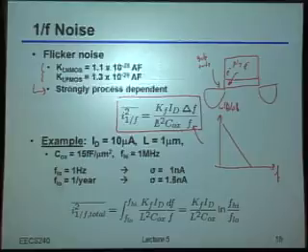Yes? Are those KFs just for strong inversion? Okay, so this is kind of bias point dependent. Yeah, these KFs most likely will be somewhat bias point dependent. So here I'm just giving you the rough number for a given bias point. You should be very careful to look into the details of the model. Particularly if you've got a good model, then it should be capturing the bias point dependent KF. But to zero order, you can take these numbers as a reasonable guess to start from, at least for our particular technology. Again, user beware, these numbers could vary quite a bit from one technology to the next.